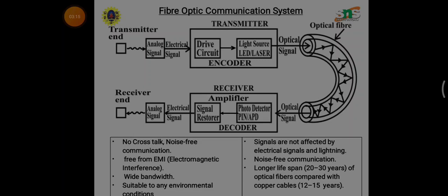And what is dispersion in optical fiber communication? Dispersion can be defined as the spreading of the light signals once they transmit through a fiber. This occurs mainly because the speed of light depends on the wavelength as well as the propagation mode. So when the light travels long distances, the small difference in speed can build up, and bit errors will happen. Similar to attenuation, dispersion will reduce the distance that signals can move within the optical fiber.